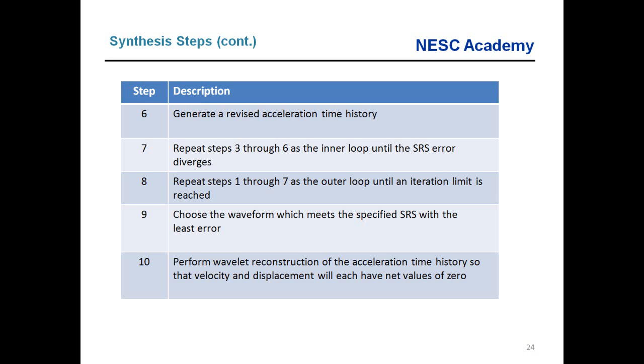And the true relative displacement between those two points might be 1/1000th of an inch. So what happens, due to significant digits and truncations and whatever, is that if we have a very high absolute displacement, we could have some, I'll call it numerical instability, for lack of a better term, that really makes an accurate relative displacement calculation difficult.